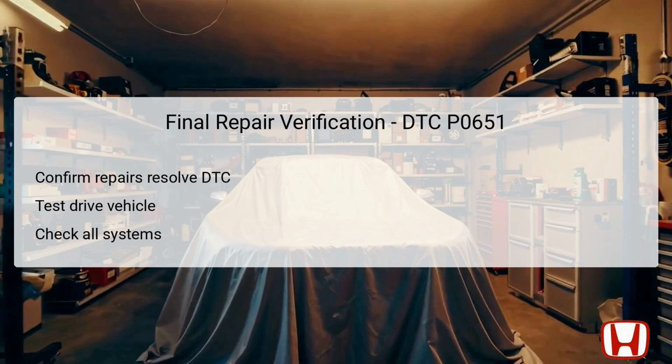The technician should then perform a test drive of the vehicle to evaluate its responsiveness, power delivery, and overall performance. It is also critical to monitor the vehicle's systems while driving, including the check engine light status. Successful repairs should result in the illumination turning off without any new DTCs presented. Verifying these aspects not only guarantees the reliability of the repairs, but also ensures safe operation for the driver and passengers.